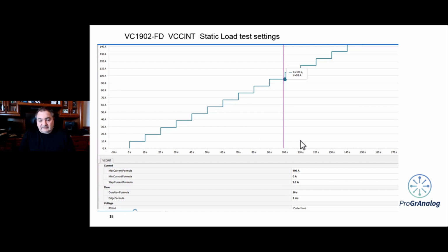If you're using the FFED, remember all the power is being dissipated through the lid. So we can slowly walk up the power curve and the thermal curve and see how our system is performing. Is the cooling solution working as desired? Do we need to increase the fan speed, if that's relevant?